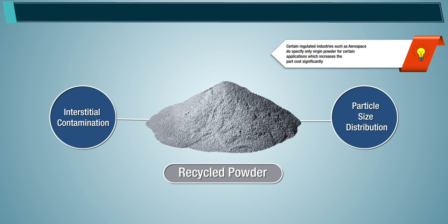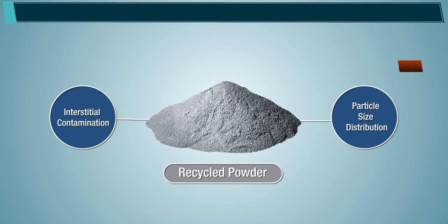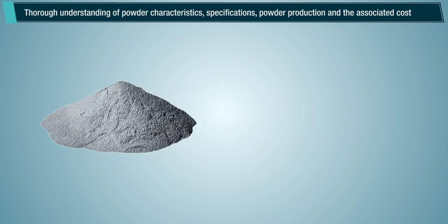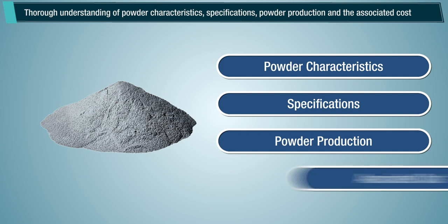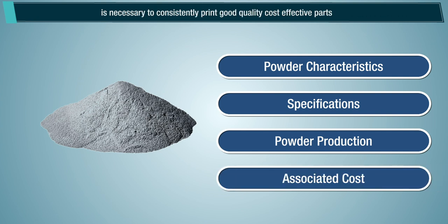Note: certain regulated industries such as aerospace do specify only virgin powder for certain applications, which increases the part cost significantly. Thorough understanding of powder characteristics, specifications, powder production and the associated cost is necessary to consistently print good quality cost-effective parts.